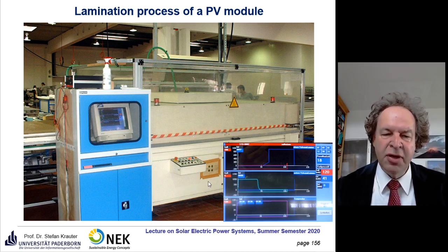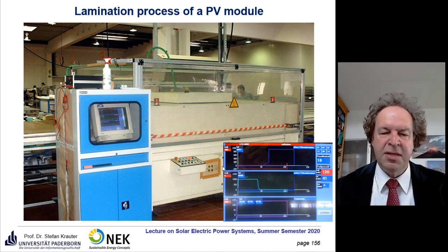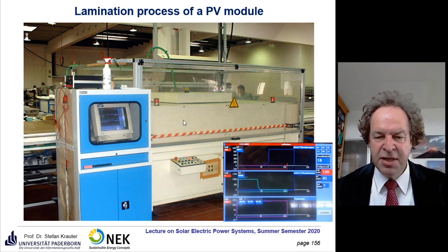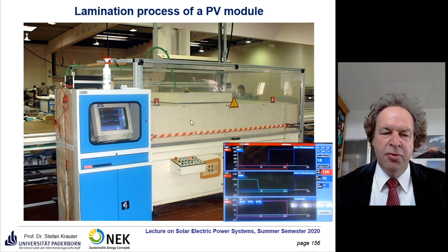It means the curing of the copolymer is carried out at different speeds. Sure, the super fast cure EVA is the most expensive, but on the other hand, you can produce more modules per hour within just a module factory. Typical temperature is around 156 degrees, and curing takes about 10 minutes.